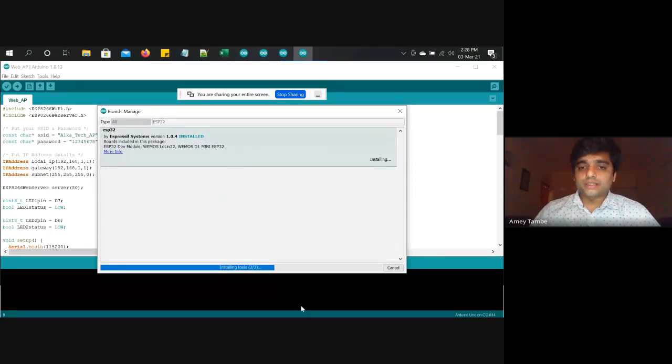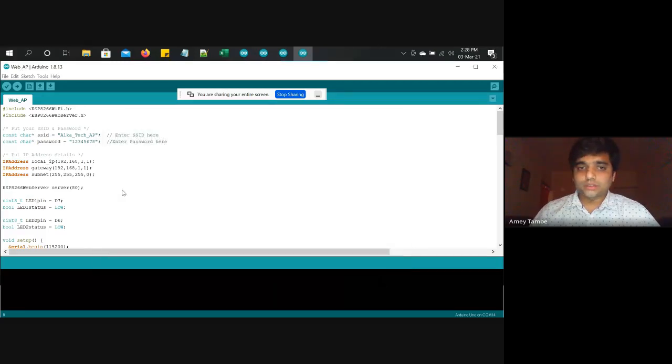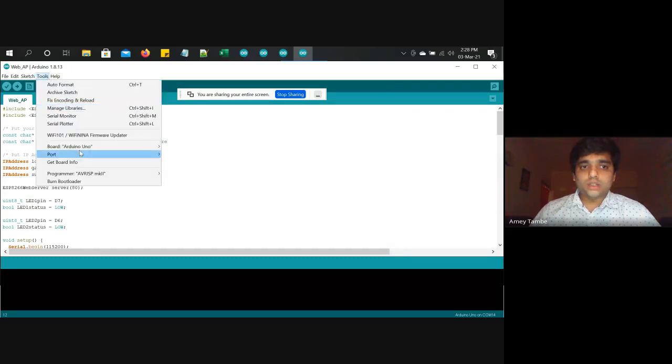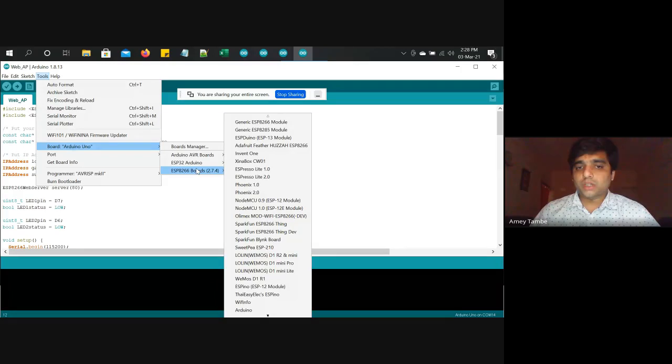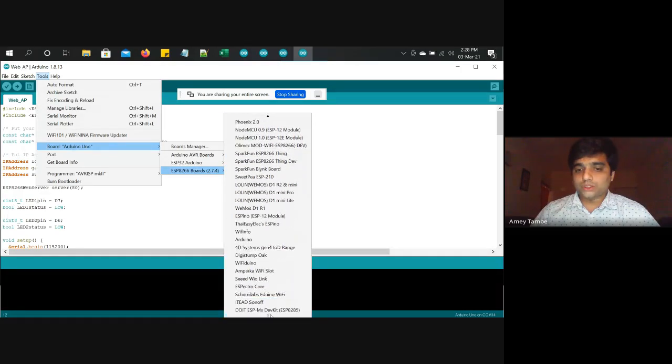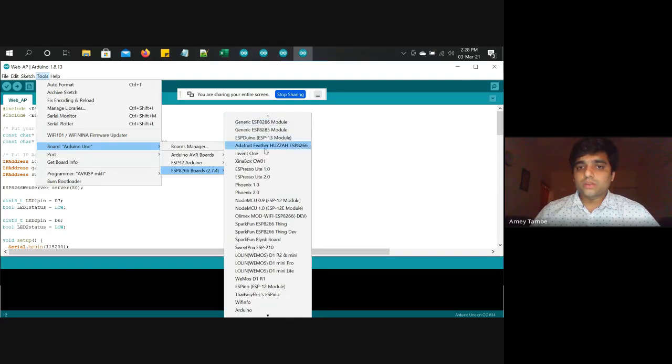Yeah, I think it is finished and it is installing the tools. It will finish in a bit. Yes, now it is installing the boards, and done. Okay, fine. So in this case, for our demonstration, I'll be using ESP8266. Then I'll select my NodeMCU version 1.0. Maybe it is here. Now these are the list of different boards.